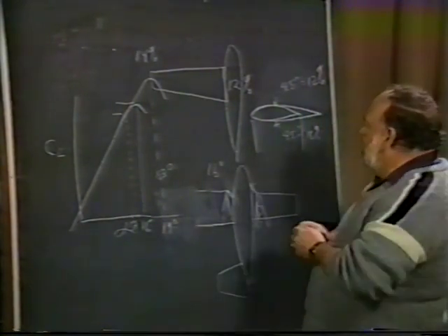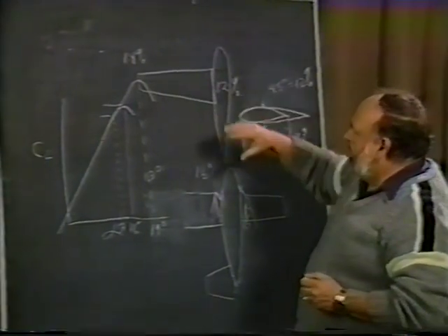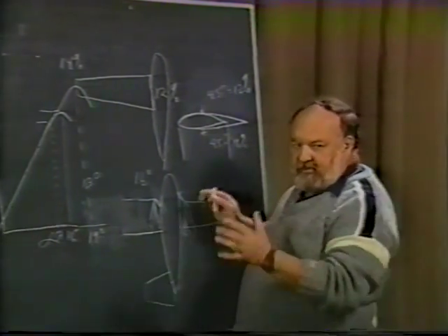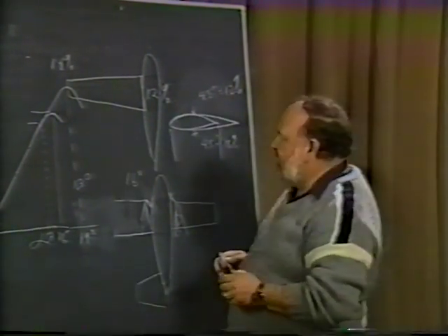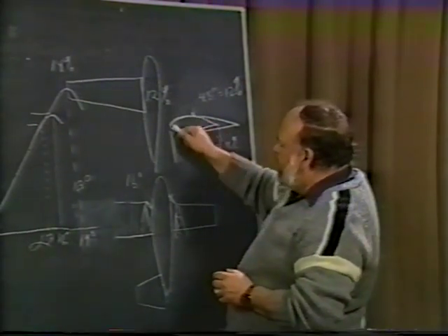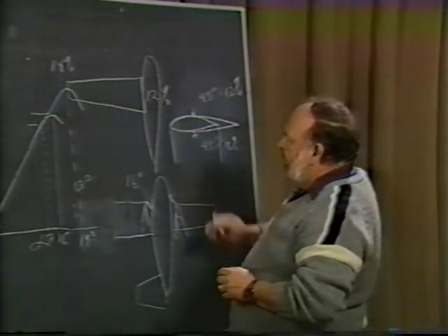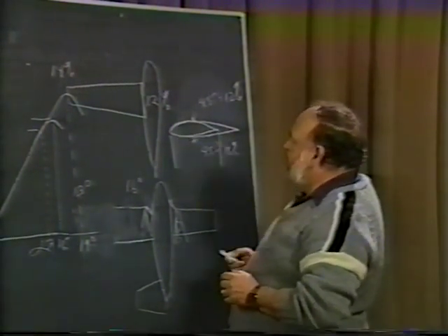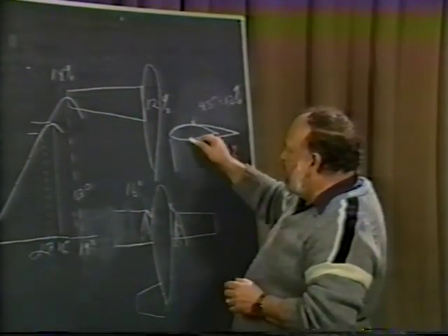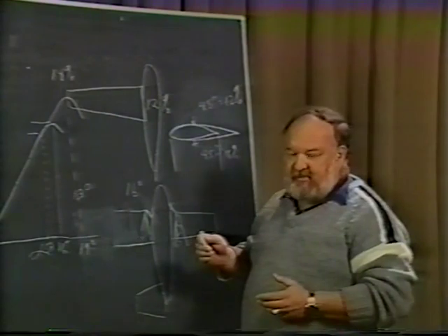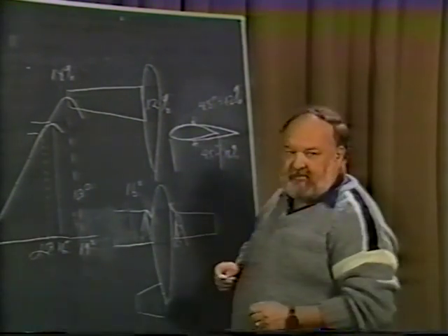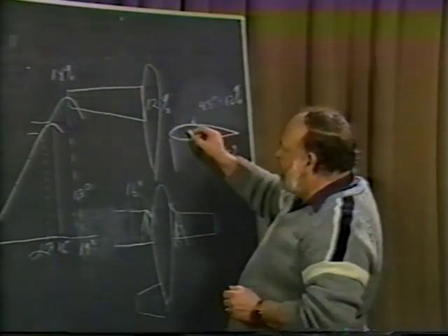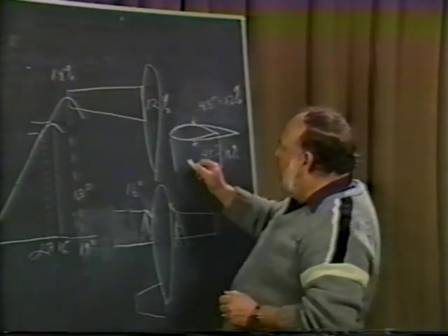So here was a situation where we had a wing design, we had it tapered, which gave us certain little advantages of being closer to elliptical lift distribution for the whole wing section itself. Yet, we were easy to construct it because we had almost the same leading edge radius. It was straight and smooth throughout. We had an equivalent thickness of the wing all the way, about 4.5 inches throughout. So therefore, in that case, when we used a tubular spar, or whether you use an I-beam spar, whatever it is, you now can have a straight spar. You don't have to bother tapering it. That has its advantages.